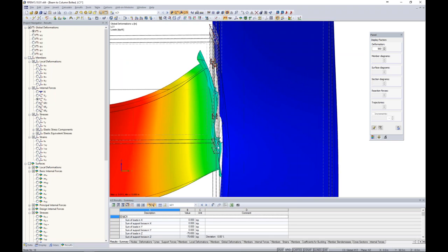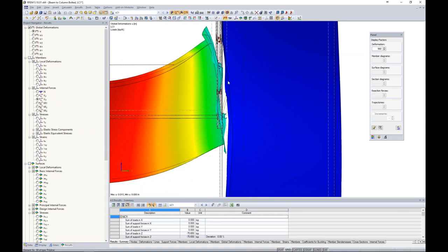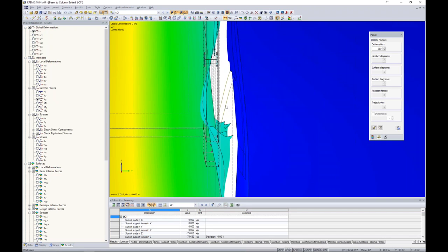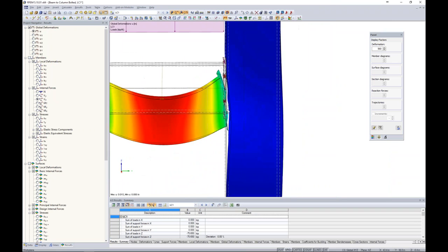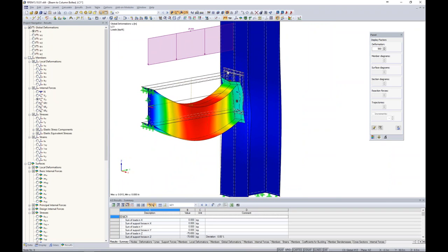As we move along the plate, in places where there are compression forces, that's where we should see the full interaction between the 2 surface elements, or actually we have multiple surface elements for these contact solids now. Here are my bolts in tension, of course, as well. So same exact concept. The only thing that I did was split that contact solid into several simpler elements.